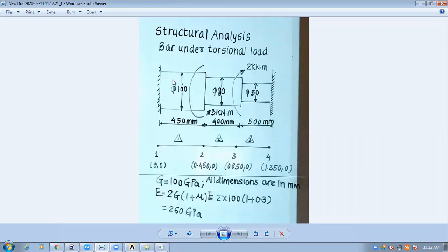See, I'm selecting the beam, so we can enter the value of a cross section. For beam we can enter the section, and in section I will select the circular cross section with this as a diameter. Now see, the properties which are available for the beam are not available for the link.